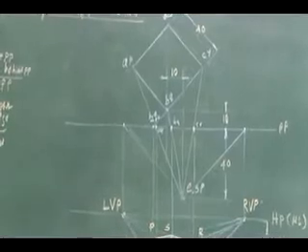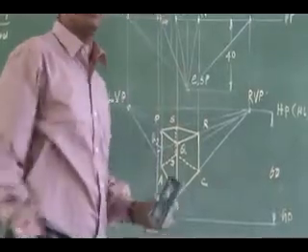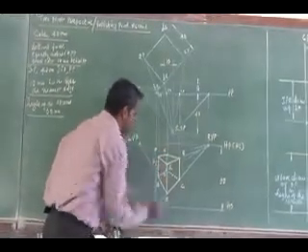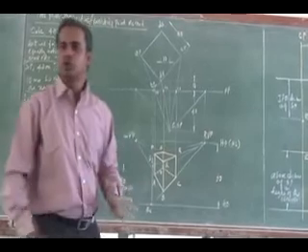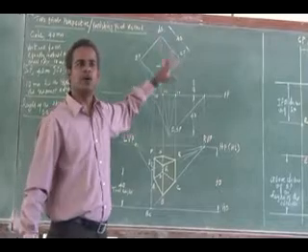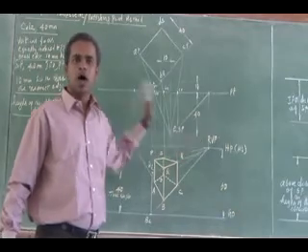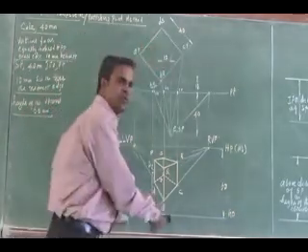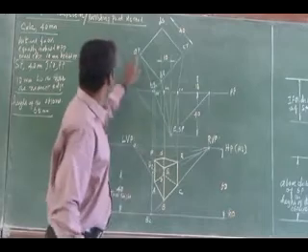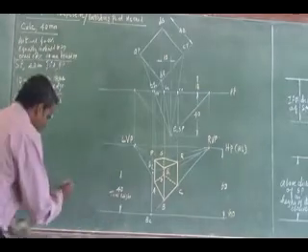You see here, this is more realistic since I have two vanishing points. One face is vanishing to the right side, another face is vanishing to the left side. So we go for 2-point perspective only when the faces are inclined to the picture plane. Right? It is up to you whether you go for 2-point perspective like this, with vanishing points like that, or for the same problem, you can draw the front view. Right? You will have 3 edges in your front view: this AP, CR and BQ edge. Similar to this, you can draw the front view.